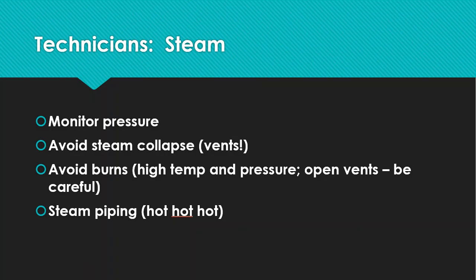Number two, avoid steam collapse. There is a chance that you've done that lab activity as well in person. The last thing that we want is some type of vat or situation where a fermenter, a bioreactor, or whatever the case is, has been superheated, super hot, and then for some reason it can't vent itself properly, and then we get a crunch, and it just collapses on itself.